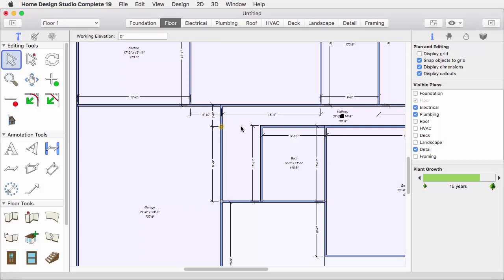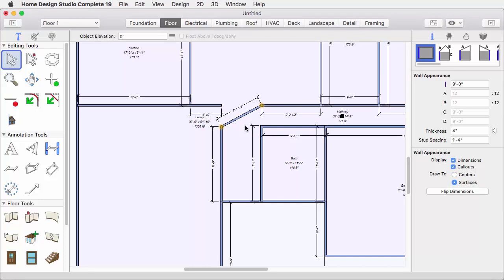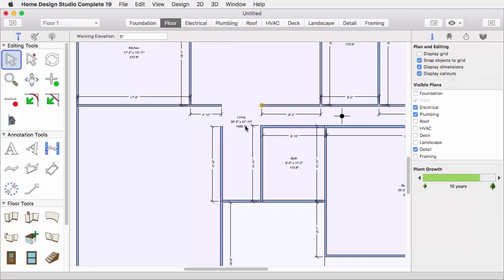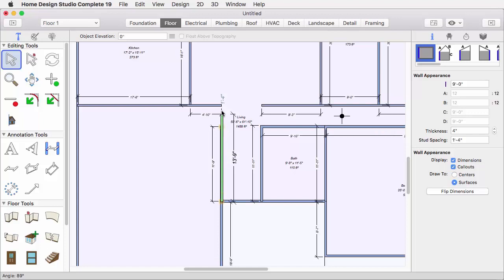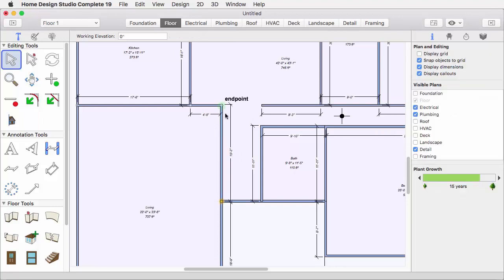You can position your cursor over a corner or wall end. Press the left mouse button and drag it to change the length of the wall. In this case, there was another wall connected to the end we moved, and now that wall is at an angle. If that wall is not needed, just select it and delete it. By dragging the end of this wall up to the corner, we will close off the desired areas again for decorating and area calculations.